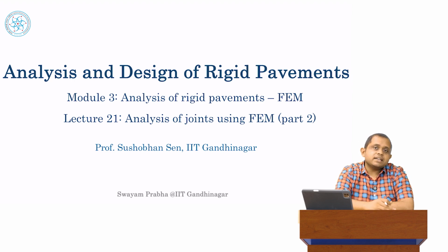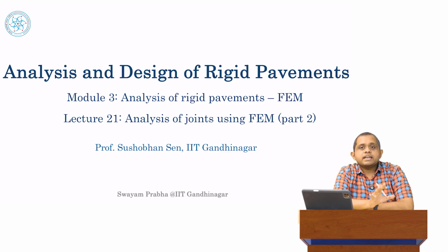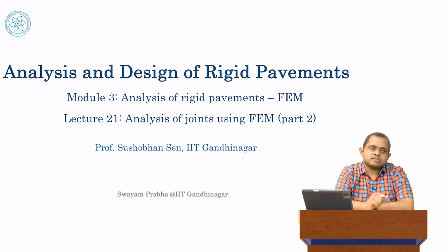Westergaard's theory and subsequent improvements tell us how to analyze slabs without any consideration of dowels. Freiberg theory tells us how to analyze dowels without actually understanding any displacements or stresses developed in the slab, besides the bearing stresses. What we do not have through analytical methods is an integrated theory of slab-dowel action. That is, how do slabs and dowels act together as one combined system? Because after all, in practice, these are one combined and coupled system.